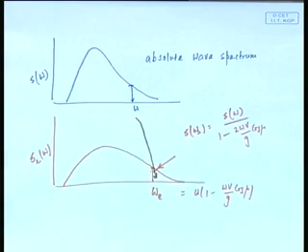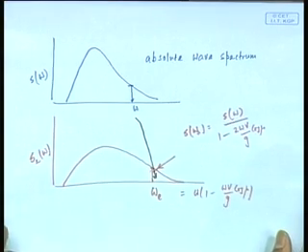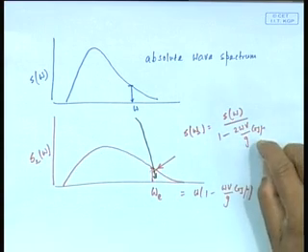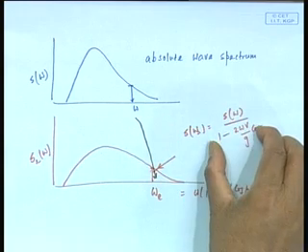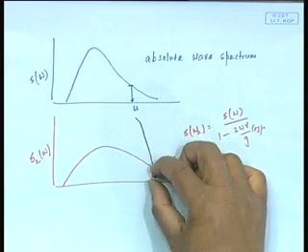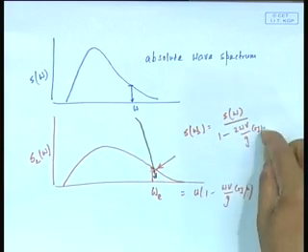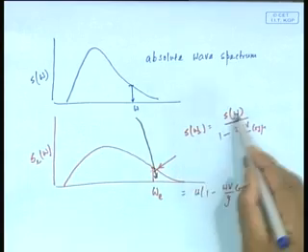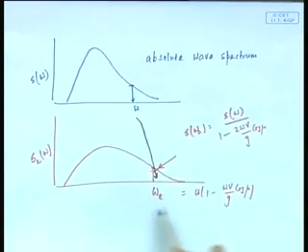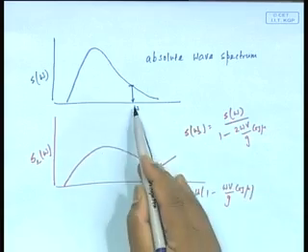See why I showed this, a very interesting point I have to show in this transformation before I go any further. Look, cos mu in a head sea, that is when the waves are coming towards the ship, cos mu is within 90 to 180 degrees. Let's say just the simple case of head sea and following sea, 180 degrees. What happened to this value cos mu? It is -1. So, this becomes larger, 1 plus. So, S omega comes down, because S omega E, see this is more than 1, right. If this is more than 1, obviously this is going to be less than this. So, this value will come down, and omega E of course becomes more because this is negative, that means this gets stretched this side.